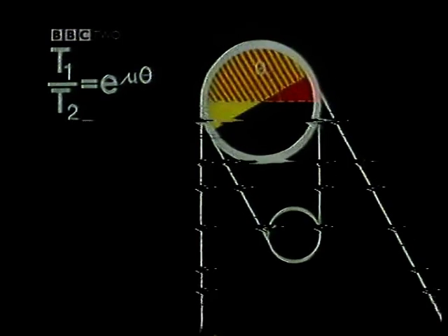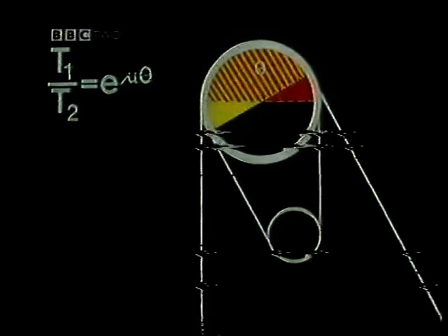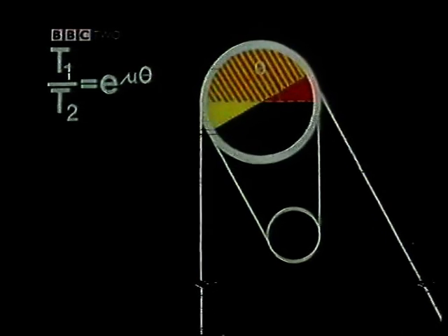This then gives an angle theta equal to the sum of the two contact angles between the rope and the sheave, thus increasing the traction. This is called a double wrap drive. Yes, we had to use a double wrap system in this case to achieve the necessary traction.